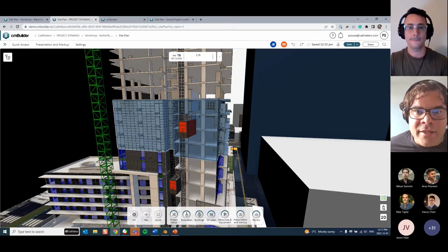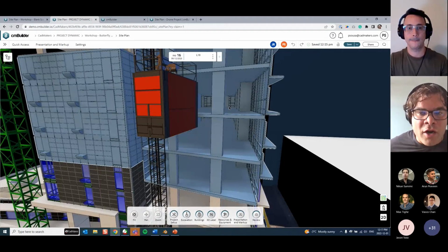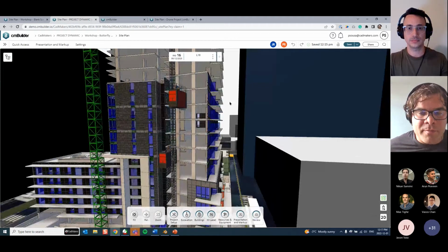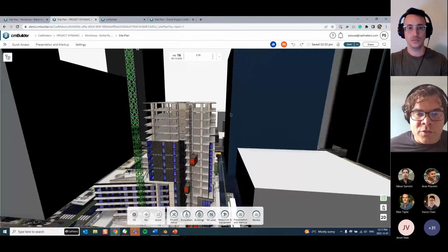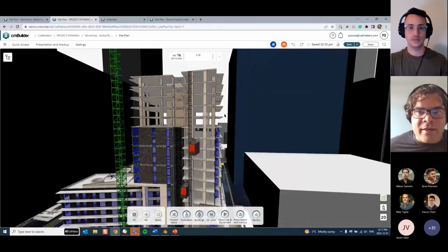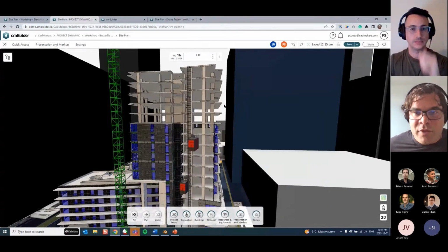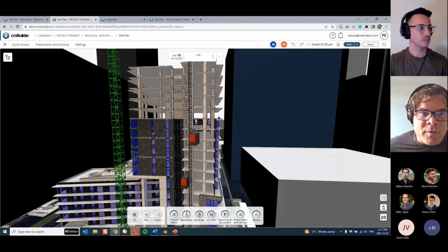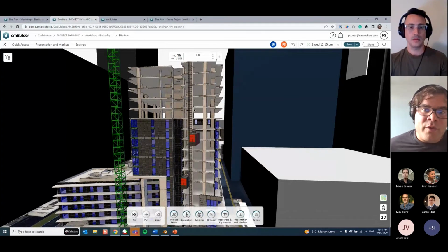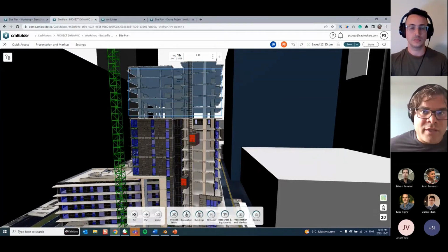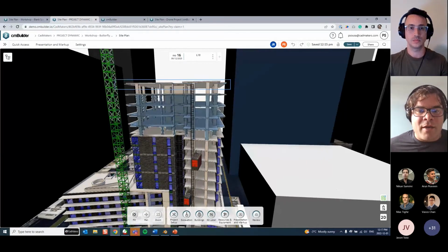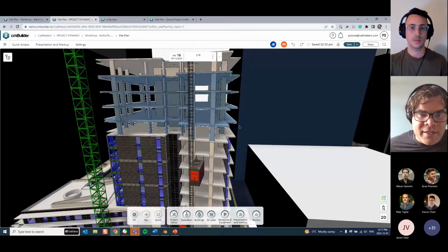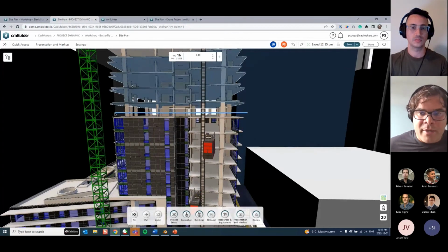Can I check? Can I add to that? For those folks that are not using the schedule integration feature, maybe they are not aware, but if you link your P6 schedule to create the milestones, and then you link the resources and the hide and show, what Pedro just said, to the milestones itself, when you sync the schedule, everything will follow, right? That's one of the benefits of linking the model to the milestones: when you do a sync based on a new schedule, it's all going to update automatically.